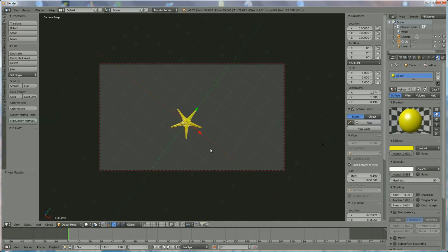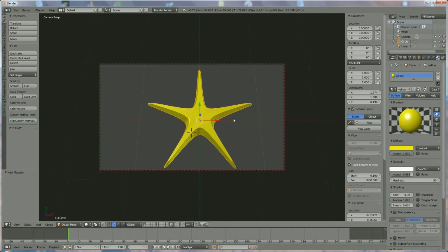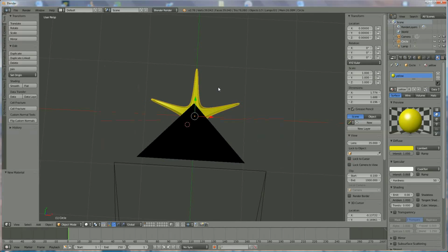Now we're going to rotate it, we're going to put the star somewhere like this, roll the mouse wheel, move it up by holding down the Shift button. Okay, this is looking okay. Now pressing unlock and pressing 0 while your mouse is at the center of the screen.